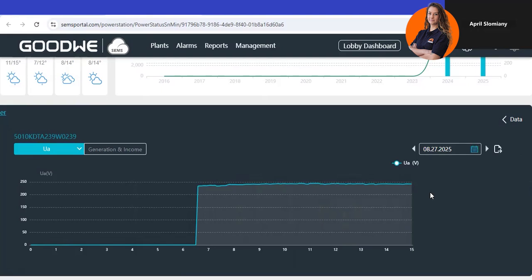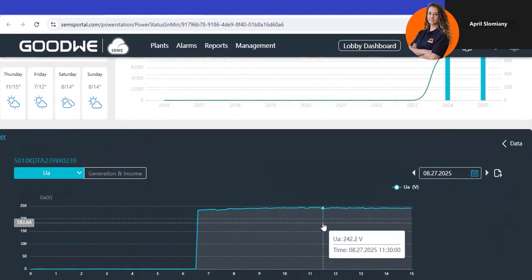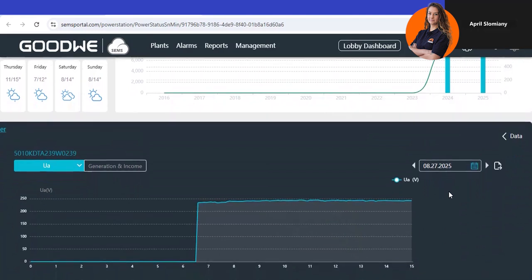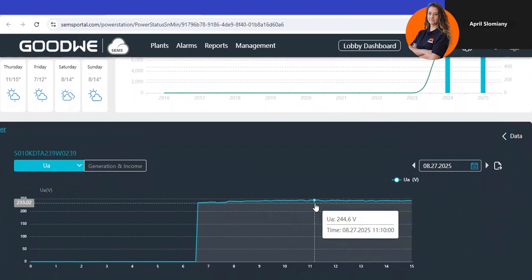You can see what we call a sawtoothing graph on your system's production. This can be caused by high incoming grid voltage. Incoming grid voltage should not exceed 254 volts in South Australia. It is mandated to remain below. If grid voltage incoming comes above that rating, your system will actually start to derate itself to protect its internal workings.